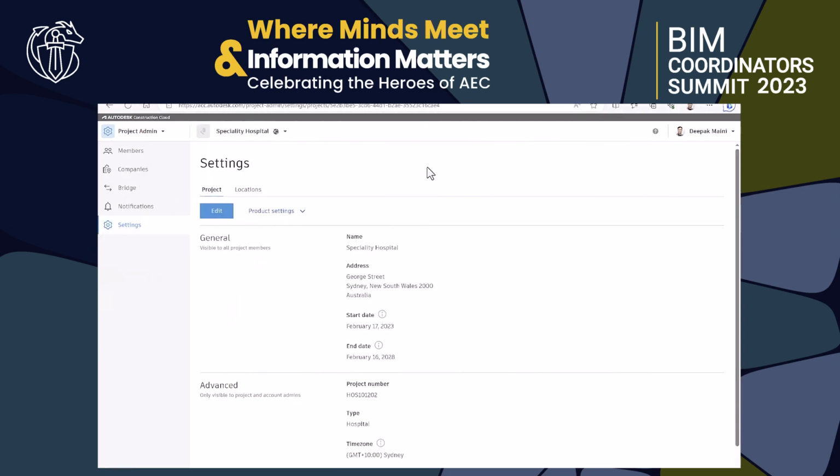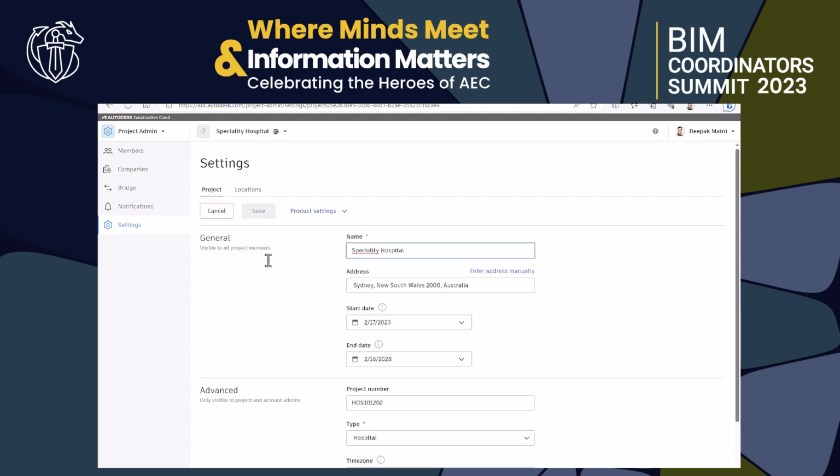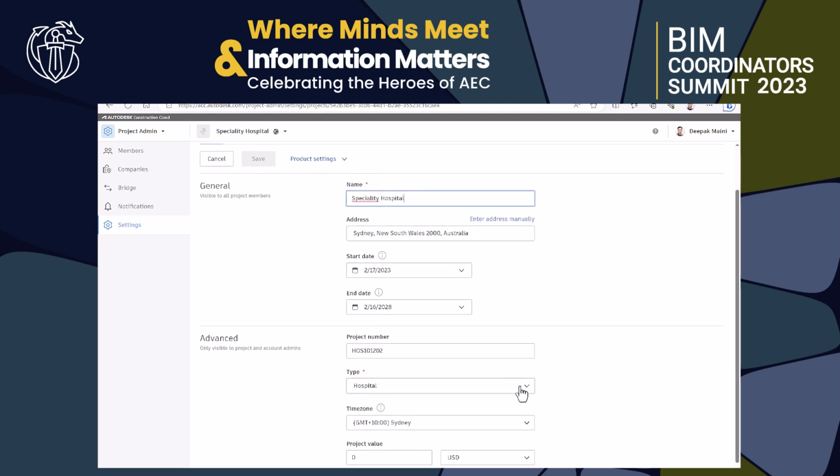All right, so here I am in the web browser, currently looking at this project called Specialty Hospital. I'm currently in the project admin page of this particular project, and under settings, you can see that my project type is set to hospital. As I mentioned earlier, the Construction IQ and machine learning based analytics are only available for projects that are healthcare, institutional, residential, and commercial type. So if I go and edit these project settings, make sure when you're creating your project, the type is set to one of these.